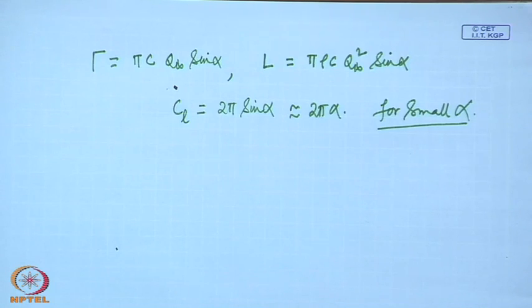A very remarkable result. With such a simple theory, the lift coefficient given by this 2 pi alpha comes quite close to the lift coefficient of any airfoil.